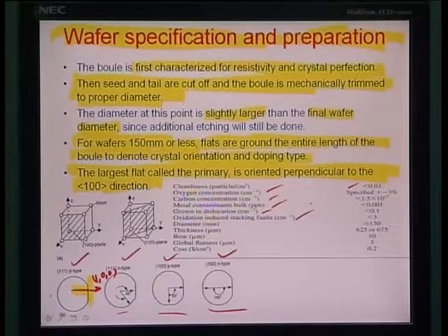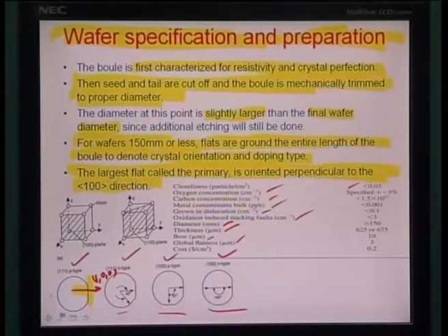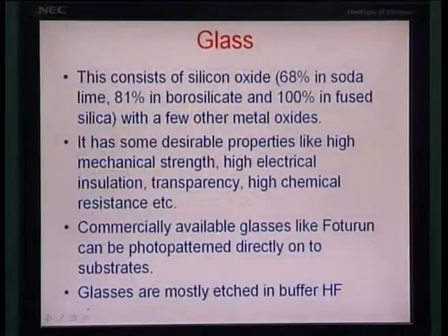You could also, this is in the volume, of course, stacking is an effect in the volume. You could talk about diameter in millimeters, thickness in microns, the bow of the wafer, how much the bowing or the warping happens, the global flatness, which is in micrometers, and then of course the cost. So these specifications are normally specified on the characterization box associated with any new wafer which comes in.